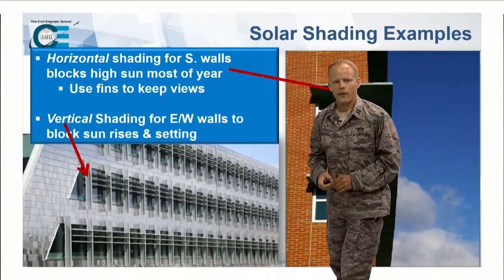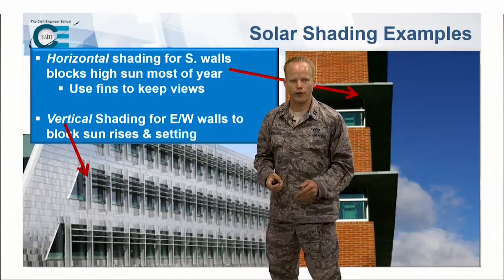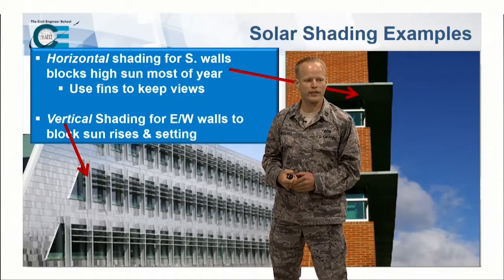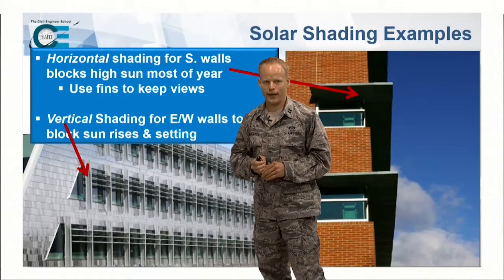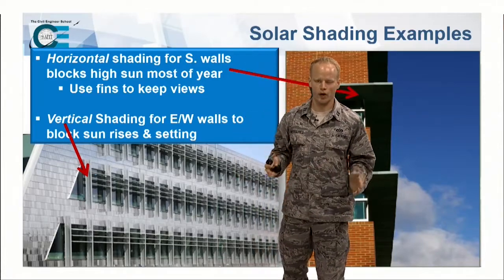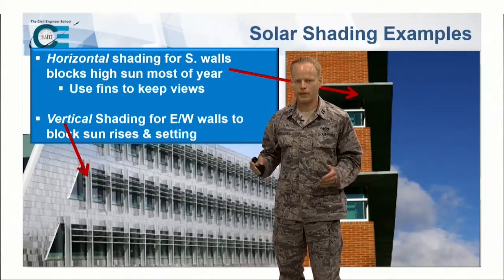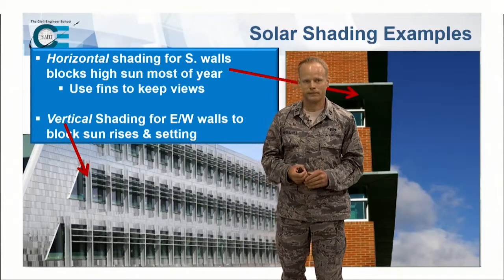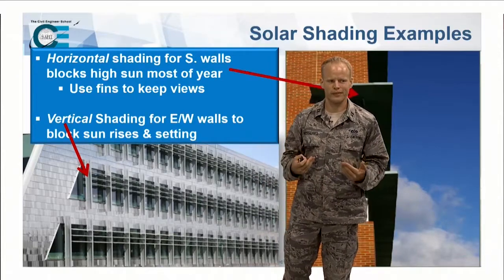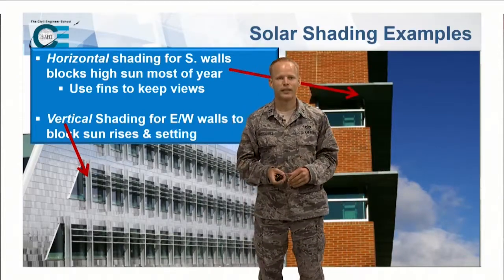Vertical shading helps on your southern face for rising sun and setting sun. The sun is very intense and very direct at that point. You may think, oh, it looks so nice, peaceful, and serene. But the sun is just as intense then as it is midday. We just don't feel it because the temperature hasn't increased.